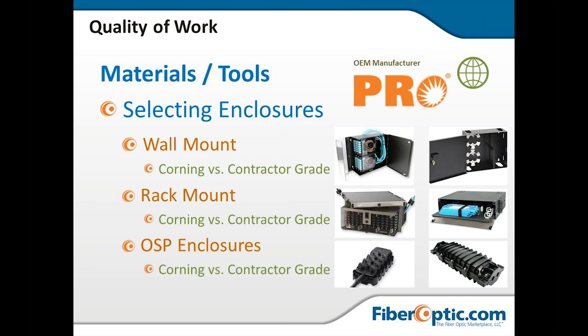At the bottom there, again, another good example of a Corning enclosure versus some other enclosures. This enclosure at the bottom is what's called an OptiTap enclosure, whereas in this other enclosure on the right, potentially you can go in there, put connectors inside that sealed enclosure, and then run a 3mm tight buffer cable out of one of the grommet holes there.